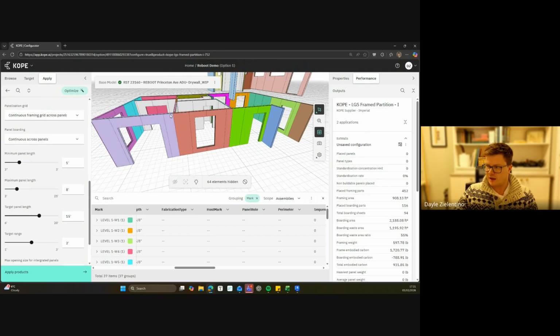I need to tell it how each corner junction detail is going to be prioritized hierarchy-wise. And what you then need to do is tell it, and I'm going to break my walls here, here. So you would go along and you would break it yourself at the 15 foot or smaller or longer, depending on what your system type allows for, and you would do that manually. So you'd break the wall into all the individual panels.